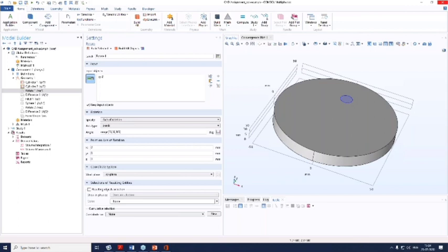Can we draw a circle in 3D? Yes, I guess you are saying the circular surface itself. You can indeed draw a circular surface in 3D, and as we discussed, in order to draw any 2D object, like a circle, in a 3D environment, you will need to use the work plane feature.